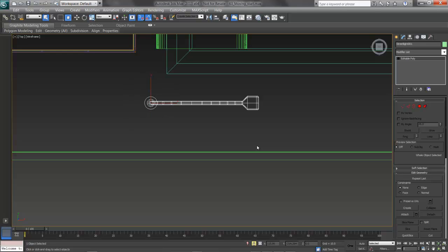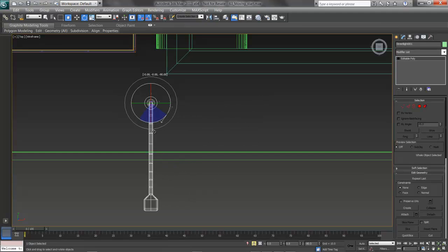I've pressed E for Rotation, and I've pressed A to turn on my angle snap up here at the top. We can snap in Position, like we just did with the Move tool, Rotation, snapping every 5 degrees until we change it, and snapping on Percent for scaling, and also spinners, when we're clicking on a spinner to move something, for example.